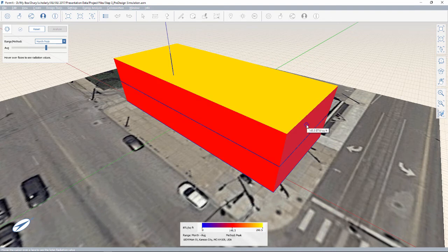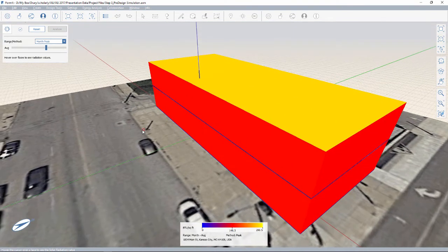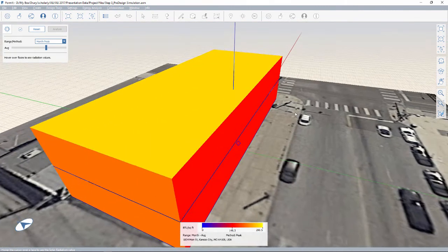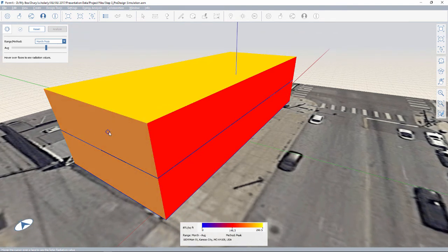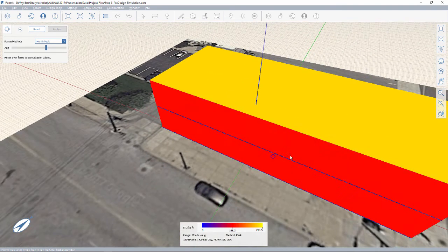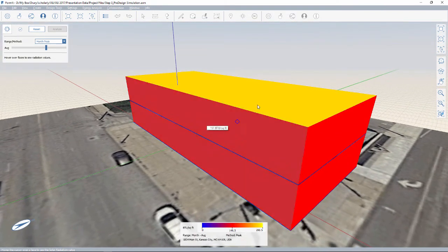On the east side, 145 BTUs. Again, on the east and the west, it's a little bit different scenario, because a lot of times it's going to be much cooler in the morning, so I can be a little less concerned about solar heat gain on this surface. But on the west, where I'm getting into 3 and 4 o'clock, you can say I'm even higher in the value on this surface as the sun's starting to set. So those are all things that I need to be very aware of as a designer, and again, that I want to communicate with the client. And then obviously the roof is baking.